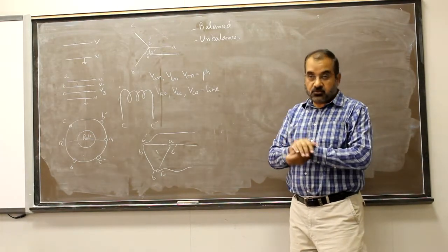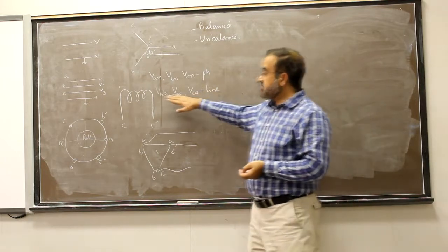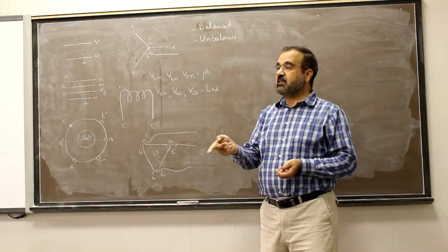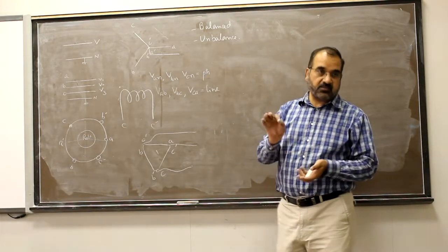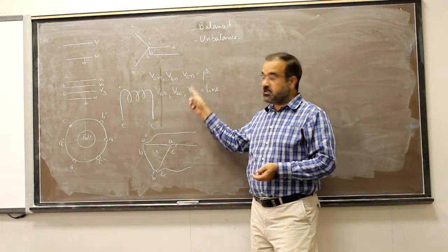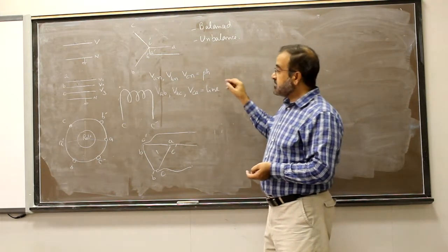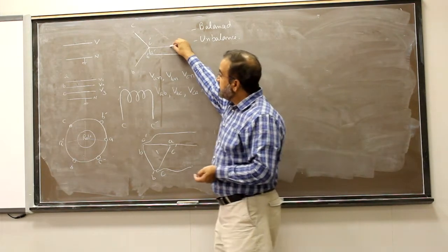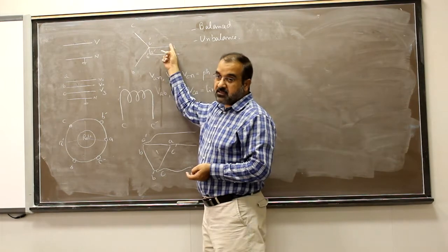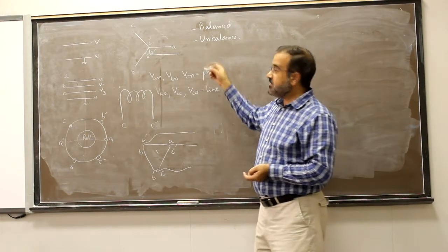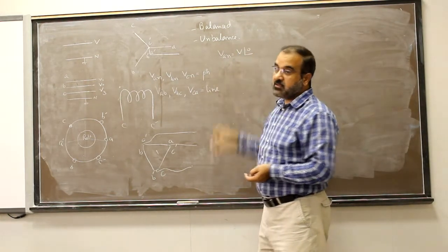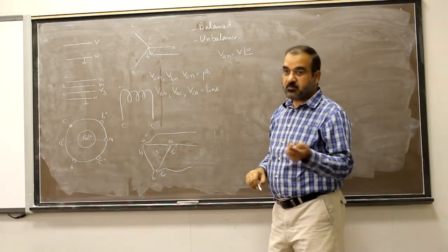Now, as I told you, I will start with phase voltages. Then I will calculate the line voltage, and then I will give you the equations for that. What is the relationship between this and this? Yes. Now I will first ask you, if I say that the magnitude of this voltage is V with angle, how much? 0. So if I say VAN, it is equal to V angle 0 in polar form. Polar form, like this.